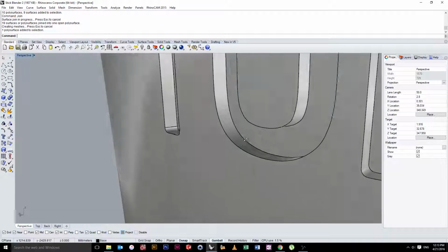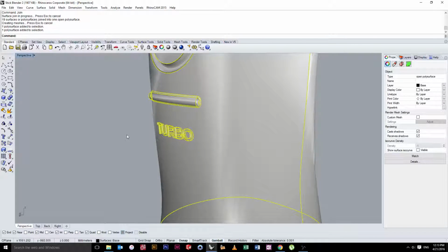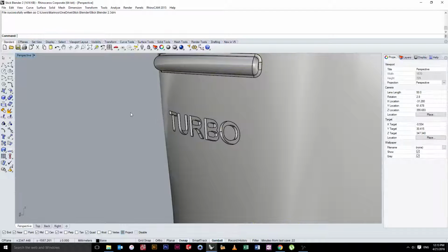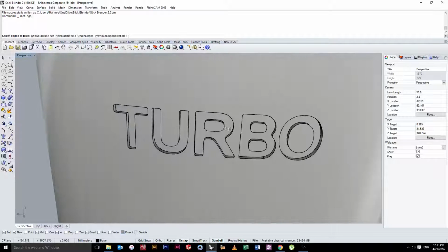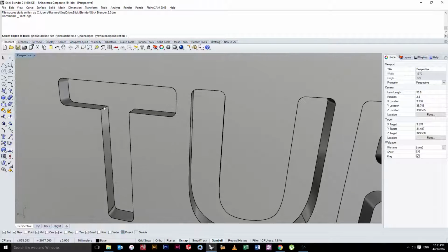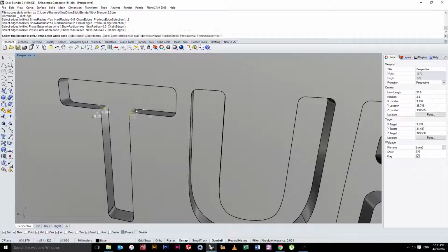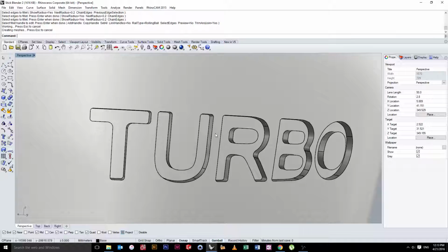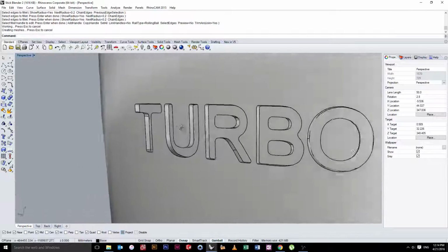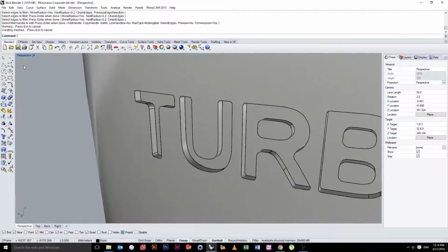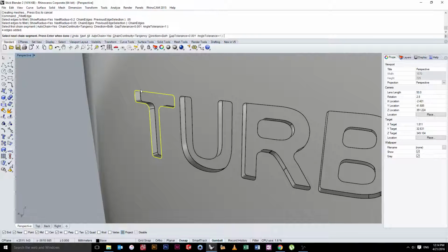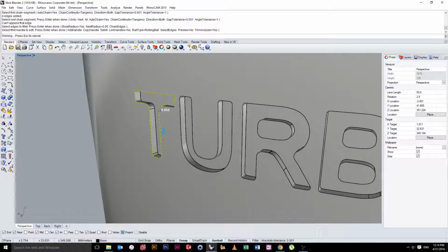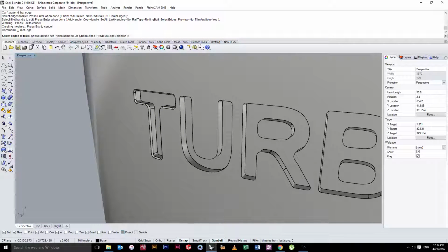Okay. Now what we want to do here is add some fillets. So at this point I would save and try to do some filleting. Solid fillet edge. No, we've missed a fillet just here, so let's put these fillets in here. I think we did 0.2, so let's just put some fillets in here. Anywhere else we missed some fillets? Okay. Let's try another fillet of maybe 0.05. We'll chain edges here. Okay, and that seems to have worked.